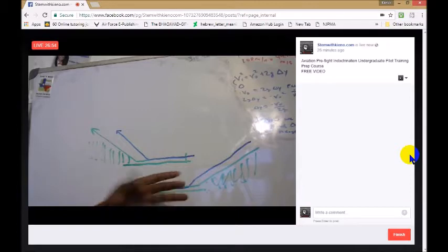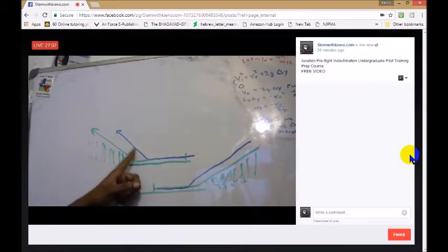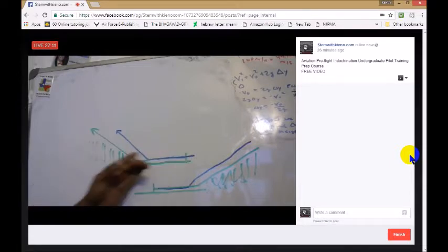And it's not good because in landing you want to land as slow as possible. So if you're slow as possible, you don't have the same amount of airflow for directional controllability, and that could be an issue. Conversely, you're also slow, but you're building airspeed. In the departure phase, you're high power, you're on the climb out, man.